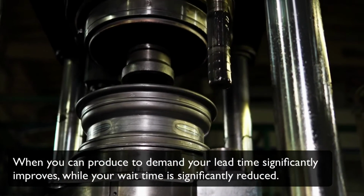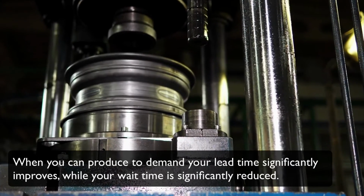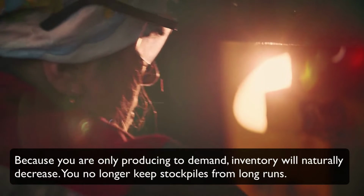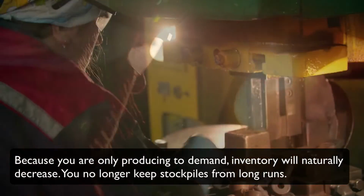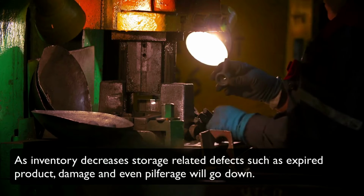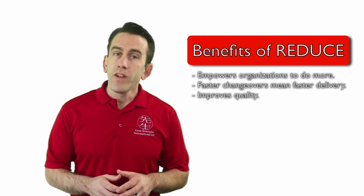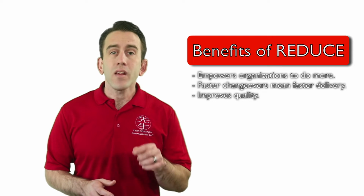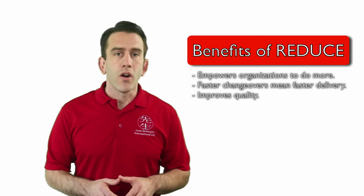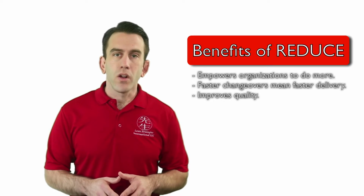When you can produce to demand in smaller lot sizes, your lead time significantly improves while your wait time is significantly reduced. The Reduce methodology also improves quality. Because you are only producing to demand, inventory will naturally decrease. You no longer keep stockpiles from long runs. As inventory decreases, storage-related defects such as expired product, damage, and even pilferage will go down. In addition to this, improving on errors that occur in the setup process drastically reduces the amount of defects and trial runs that occur. In fact, if a defect were to occur in an improved changeover, it would be easier to spot because the lot sizes are much smaller than in a traditional setup.